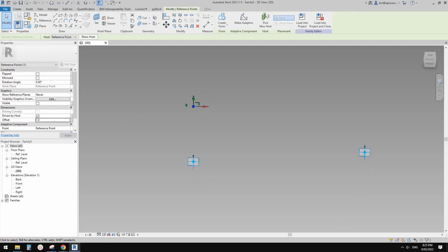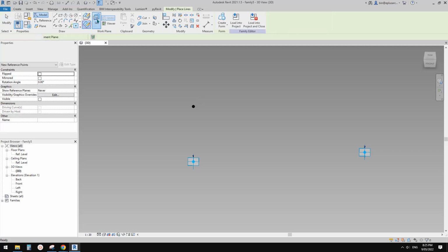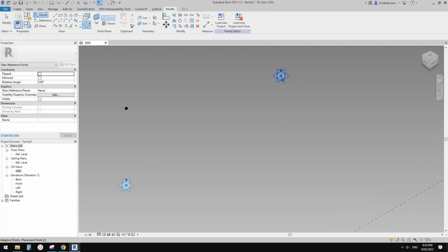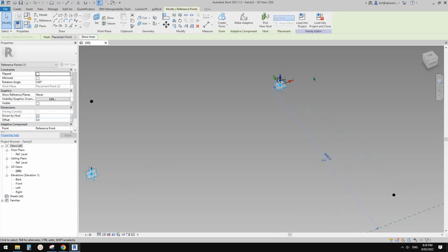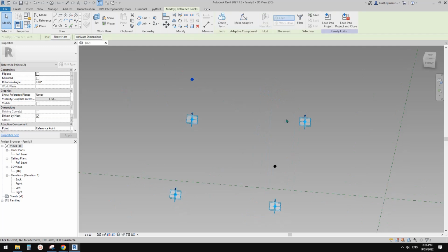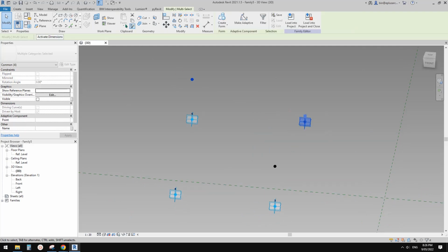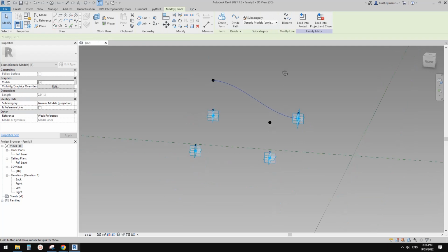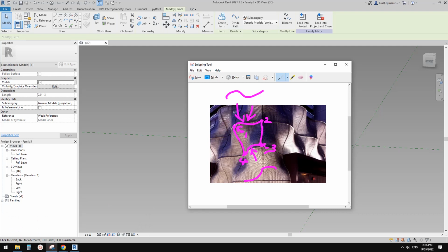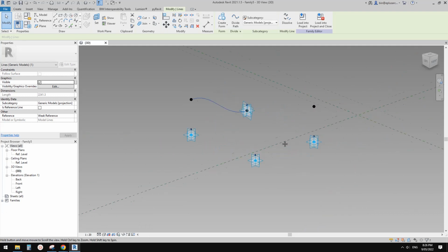So 1, and another one, draw on work plane, set work plane. Pick this and place on point 2. This time, see these arrows pointing that direction, so we just need to type in -1. Now we can select these 2 points, control select these 2, and then we can create a spline. So this is this line. Then we just need another one on this side.